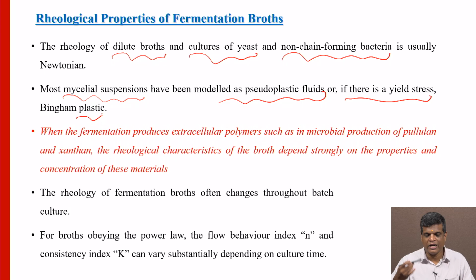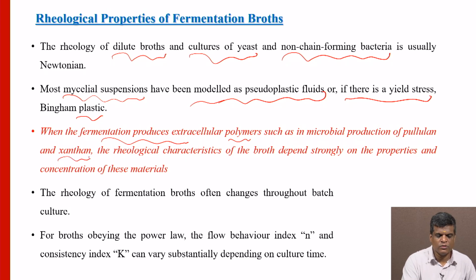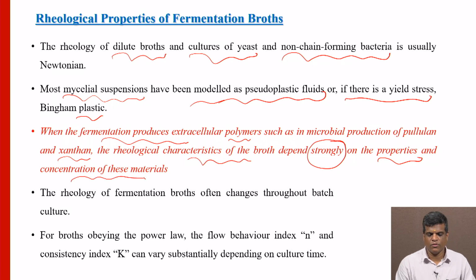I think we already discussed very thoroughly what pseudoplastics and Bingham plastics are. Then, when the fermentation produces extracellular polymers, such as in the microbial production of xanthan, the rheological characteristics of the broth depend strongly on the properties and concentration of these materials. That is what they want to mention here.